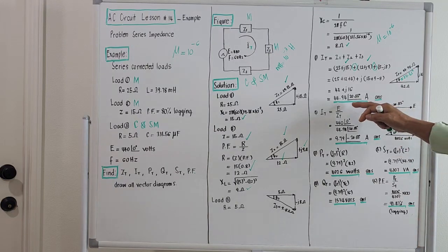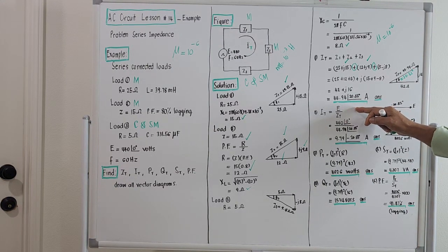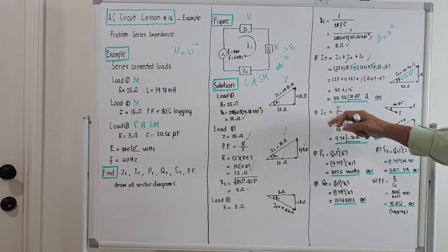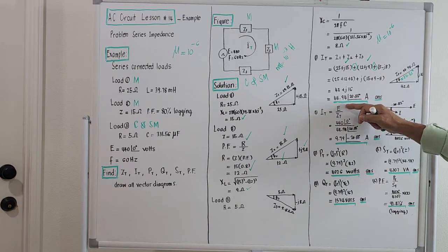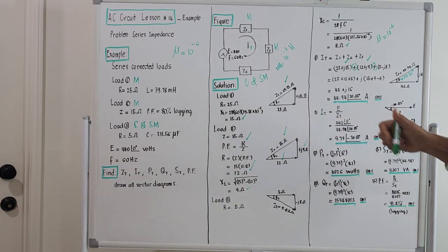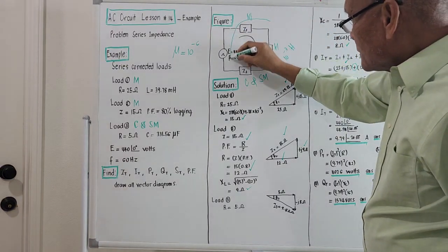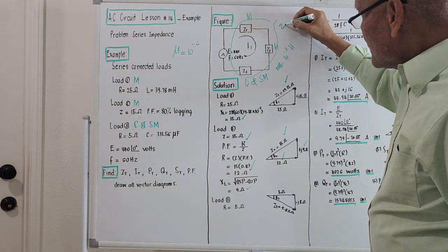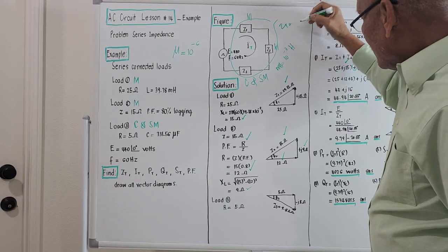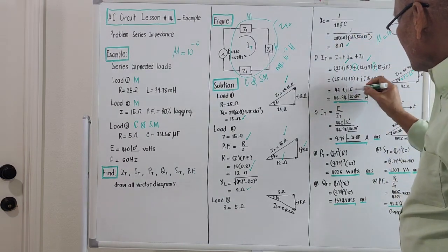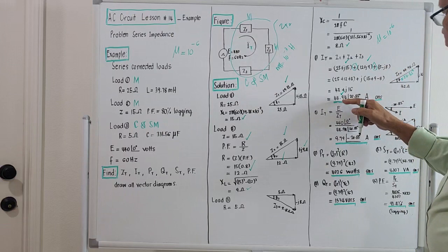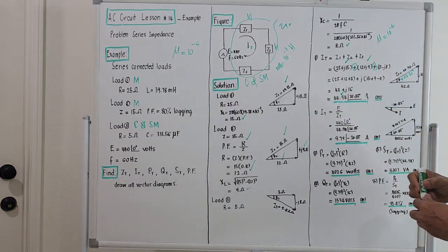Okay, so we are now given the total impedance. So total current will be the voltage of the source over total impedance. Because we have compressed this one already. We compressed it already, right? As a single impedance Z total. And that Z total is actually this one, 44.94 angle 20.85.